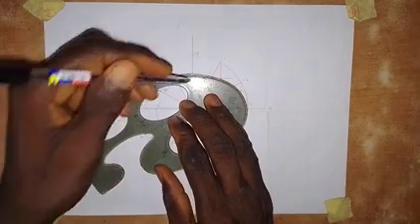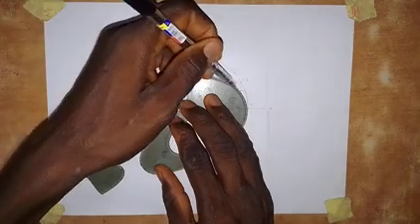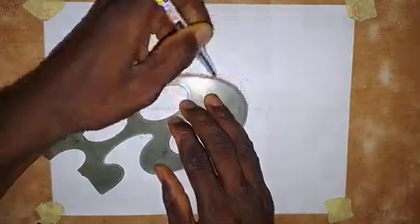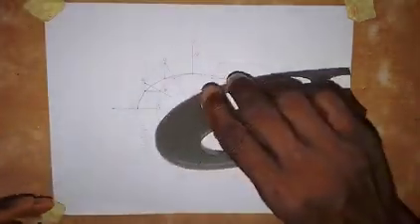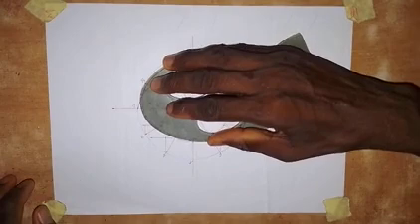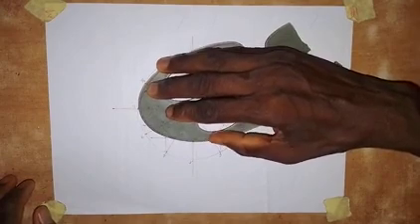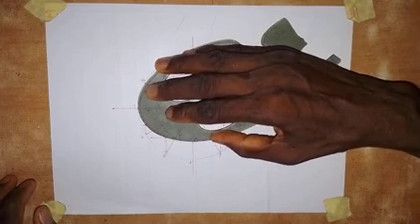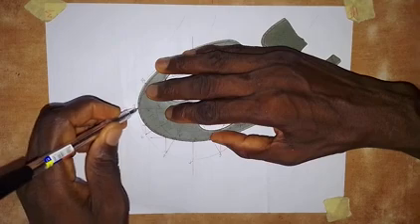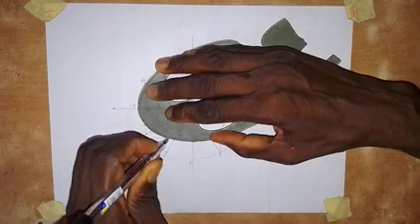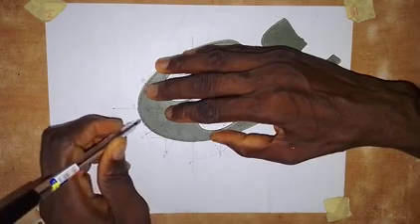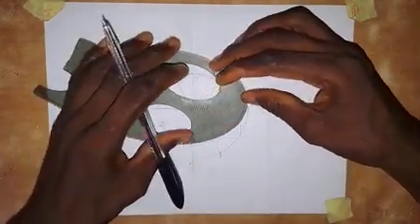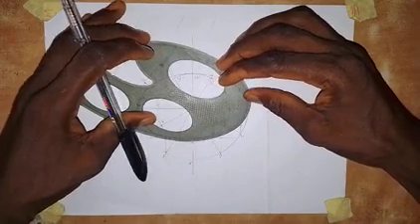So from this point here, we draw like this to point 1 on the major circle. Alright, then we turn it down here like this. We adjust the French curve to make sure the points are aligned on the edge of the curve. So it goes in this direction, to this point. Alright, then we turn it to this side. So we're almost done with the curve, with the ellipse.